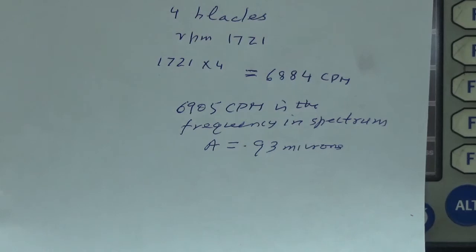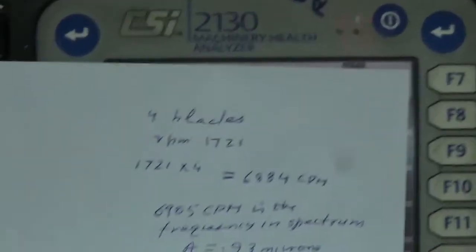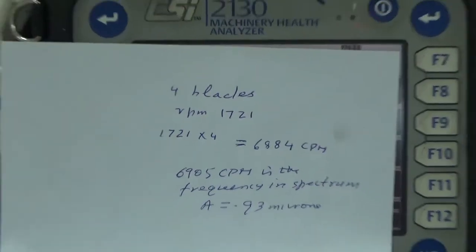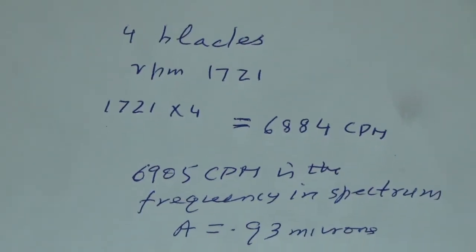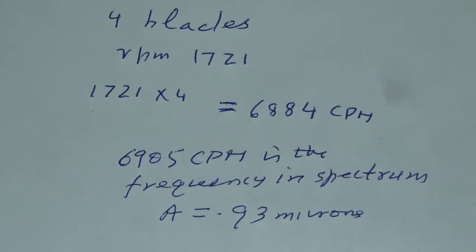Now the amplitude at this frequency, 6905, is telling me with how much pressure the blades are touching the cover plate. Okay, I think you can see it now clearly.